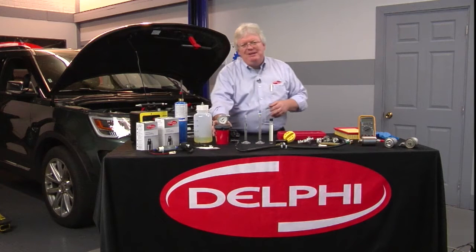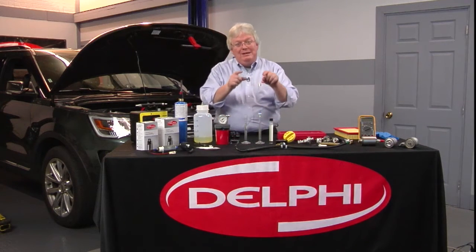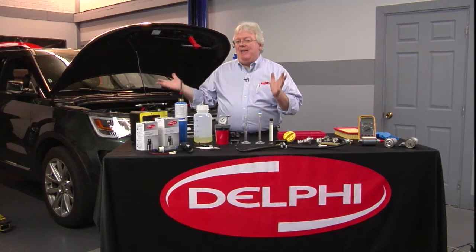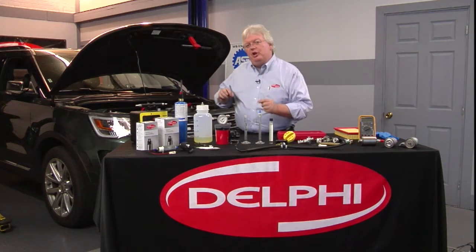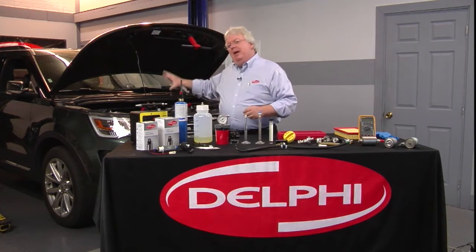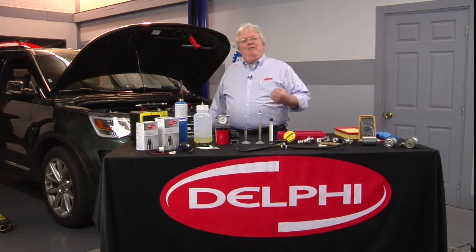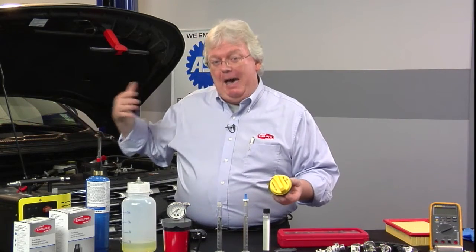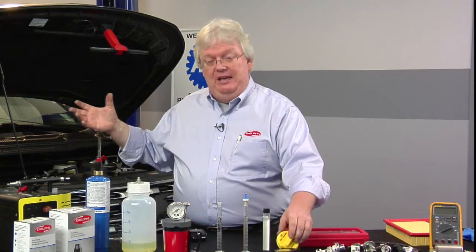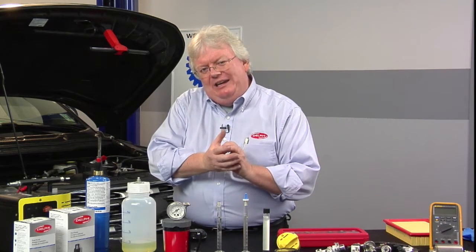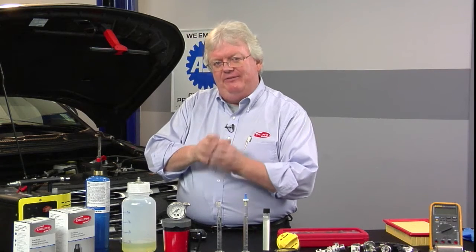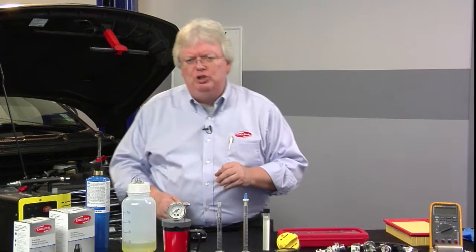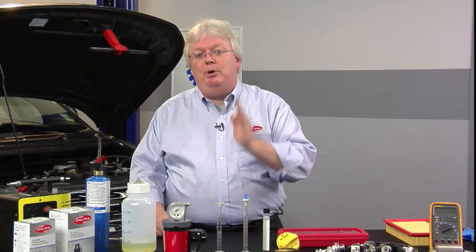So this is not as big of a problem as it's been in the past, but what is a big problem now with not only E10, but E85, the flex fuel, is in vehicles that aren't flex fuel, like right behind me, a late model Ford, that would have a traditional yellow gas cap, or in the case of the capless vehicles, we would have yellow writing on the filler neck that says E85. This one says E10 to E15. E15 is not really out there too much yet, but E10 is about every gas pump you get.